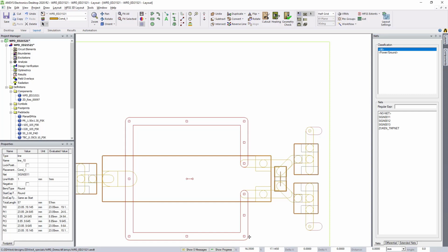I can do some changes. So this is a power splitter, so the quarter of the wavelength, I want to change some of the length here to adjust it slightly. So I'll modify both to keep both branches matched.